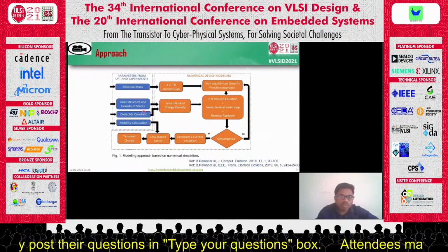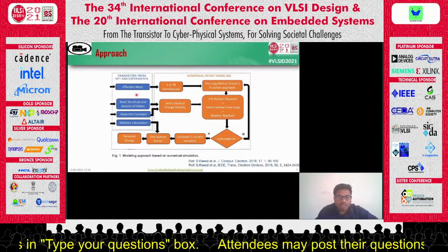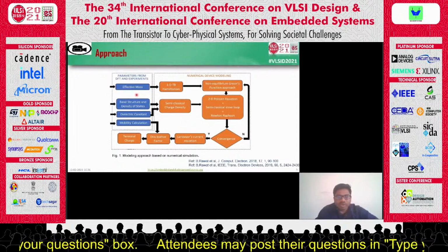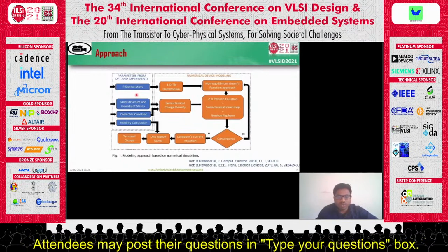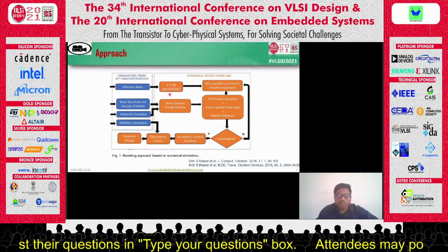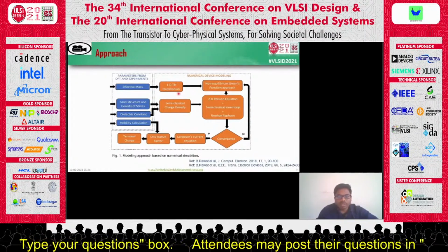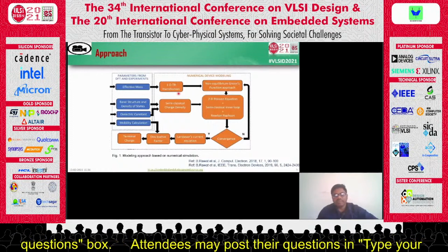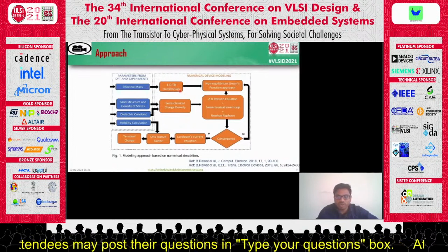Let us discuss the approach we have adopted for the simulation of the devices. We have adopted the NEGF formalism to incorporate the quantum effects and the essential physics of the 2D material, for which we have developed a 1D tight-binding Hamiltonian that depicts the whole device, in which we have taken the effect of source and drain by accounting for the self-energy matrices in the 1D tight-binding Hamiltonian.